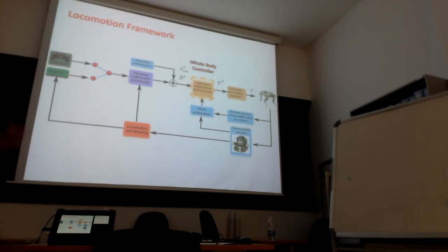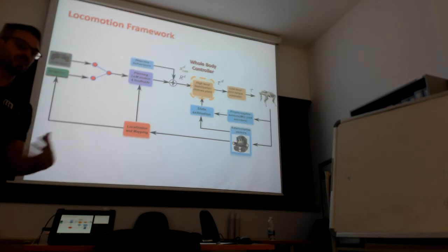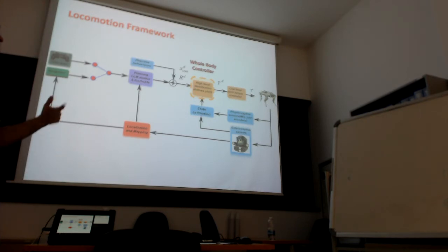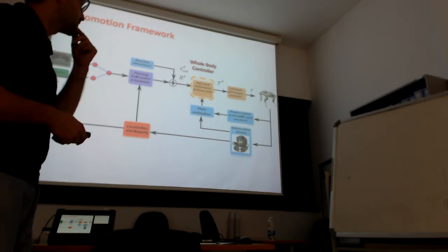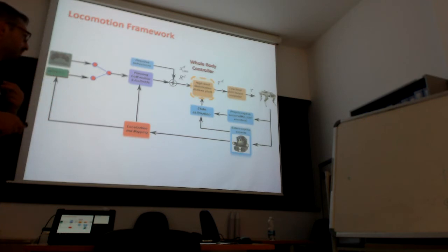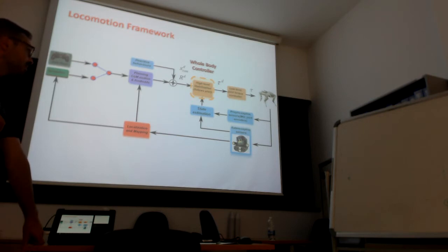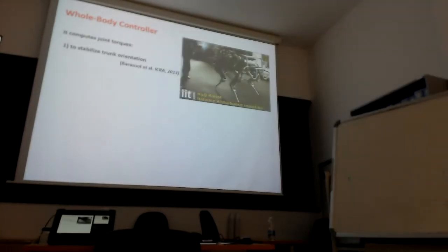From encoders you get the odometry, which is an estimation of the velocity of the base that you integrate, and from the IMU also you can get an angular velocity that you can integrate, but that is prone to drift. So merging the two, you take the best of the two approaches and you try to find a better estimation. If you also add vision, estimating how the visual flow changes, you still have a third input that improves your estimation.